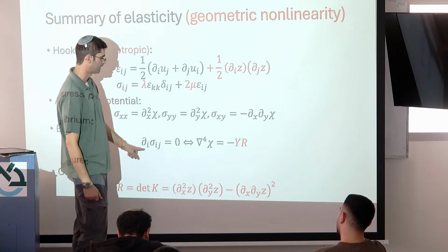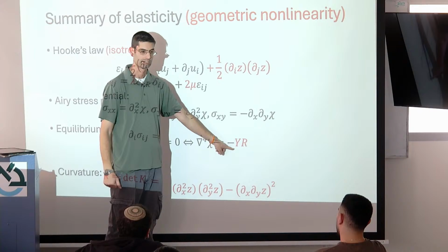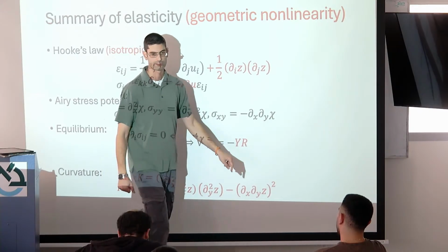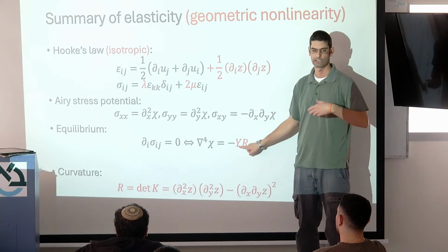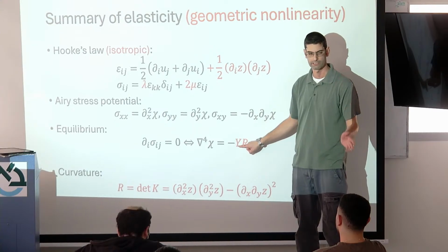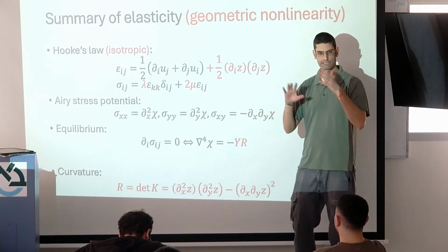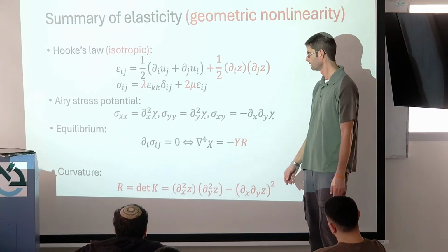In terms of the relevant equation, what happens? You get a source term. Okay? The right-hand side is no longer 0. 0 is only when it's flat. Instead, you have Y, which is again an elastic coefficient. It's equal to E times the thickness divided by 1 minus the Poisson ratio squared, or some set of functions of these two guys. That's in the notes if you're interested.